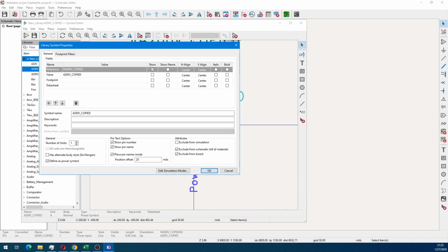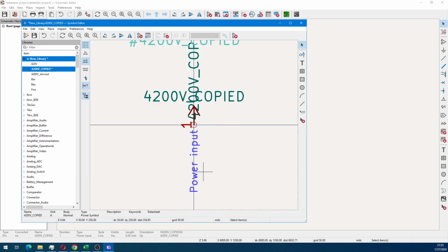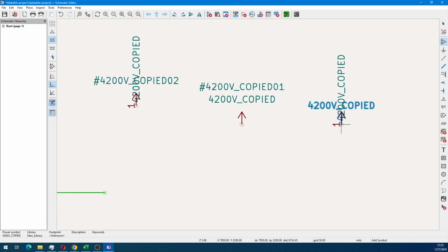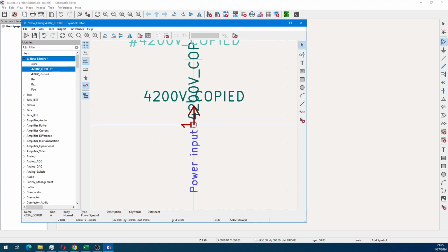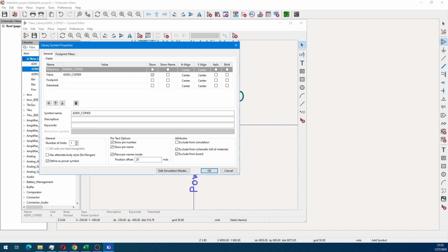The last note that I have on this is, depending on what company or agency you're working for, with components that have subunits, instead of U1A, U1B, U1C, you might be required to put a dash followed by a number, or maybe a dot between the base part and the subunit part, or the letter. So KiCad, of course, lets you do this as well. What you do is, in your schematic, go to the top left, almost in the corner, and you'll see a settings icon. You want to click that, and you'll get an option to change the formatting for those subunits.